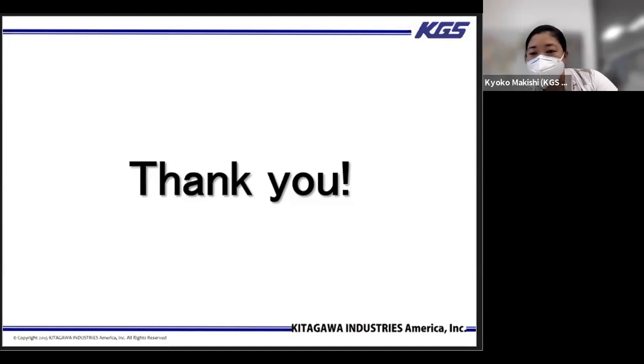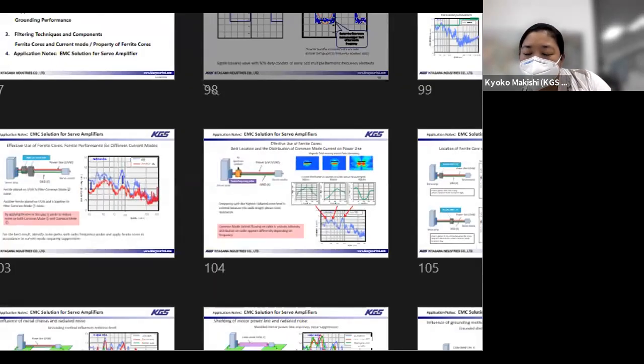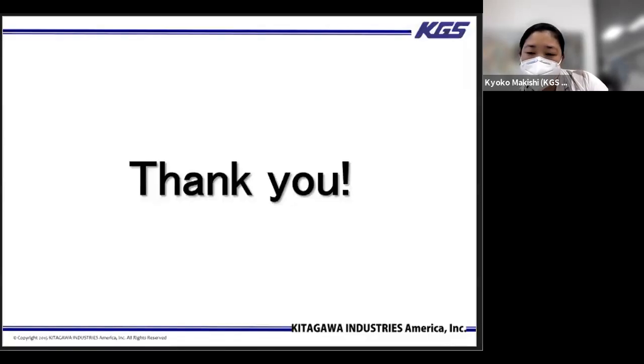Okay, so I'm back. After talking with Yumi-san, he's not sure if there's a situation where the AC and DC would be really close to each other. They should be separate anyway. But generally, the more concerning one is the AC. That one definitely should be shielded and grounded really well. DC is not necessarily the noise source or noise issue as a general comment. So that might not be the one of concern, but the AC one might be one that you want to take a closer look at.